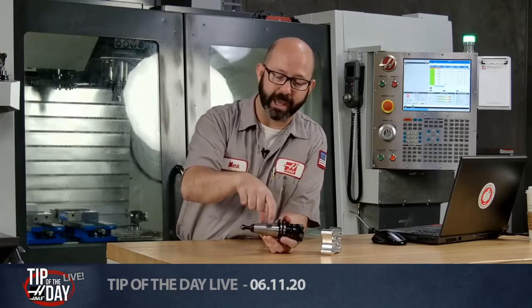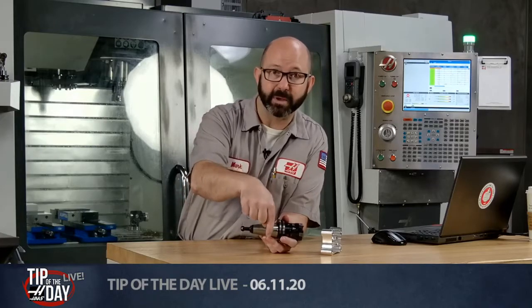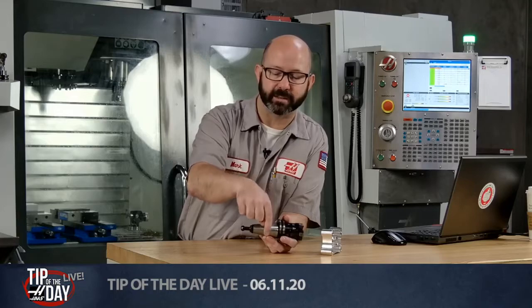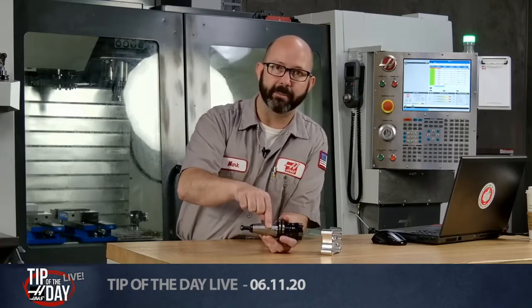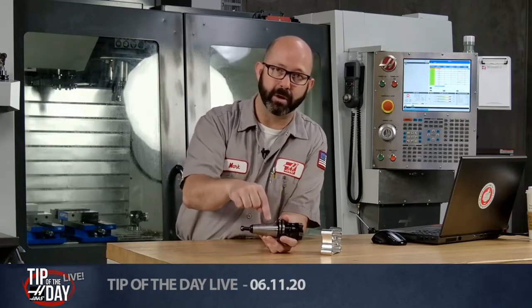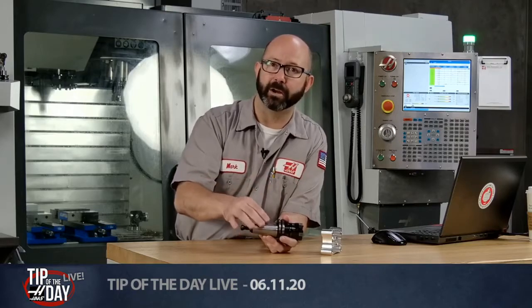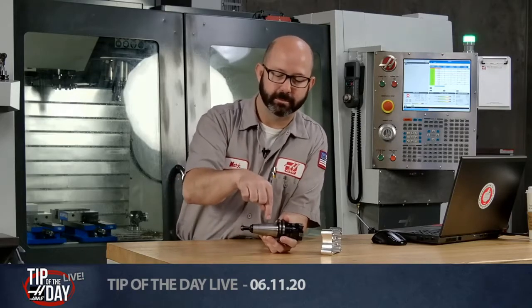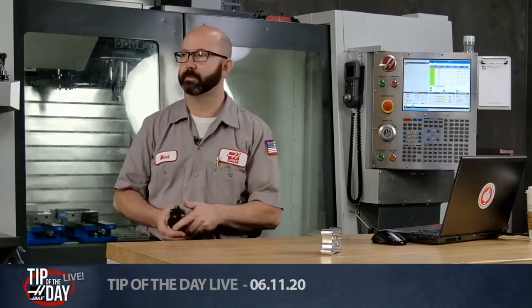In that case, you don't have to be perfectly at the high spot. Like if you were using an indicator, I might just indicate the high spot. But even if you're on the rampy angle, it's going to find the center of the bar. After you find the center of the bar, go to G54 Y0. Then reprobe the top of that round thing, and you'll have all the information that you need. So it's all right there in the templates in VPS.